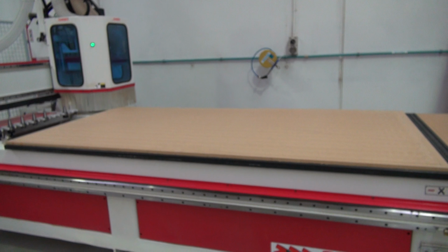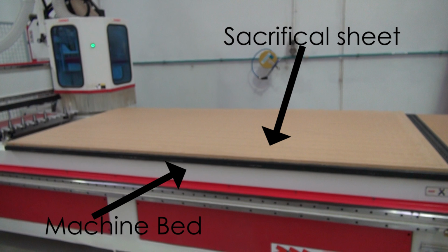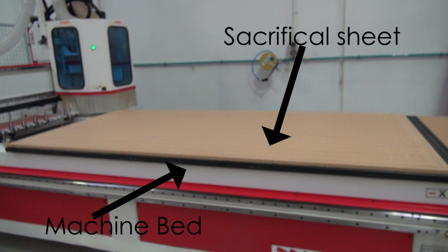The CNC machine uses a sacrificial sheet during all operations. This sacrificial sheet protects the machine bed and other components, and also acts as a protection agent for the material. Through the vacuum pumps, it also ensures that the sheet is secure during drilling and cutting operations. Over a period of time through machine usage, small cuts are made in the sacrificial sheet. When there are too many cuts and the depth of the cut is too deep, the vacuum will drop, causing parts to move during cutting operations.